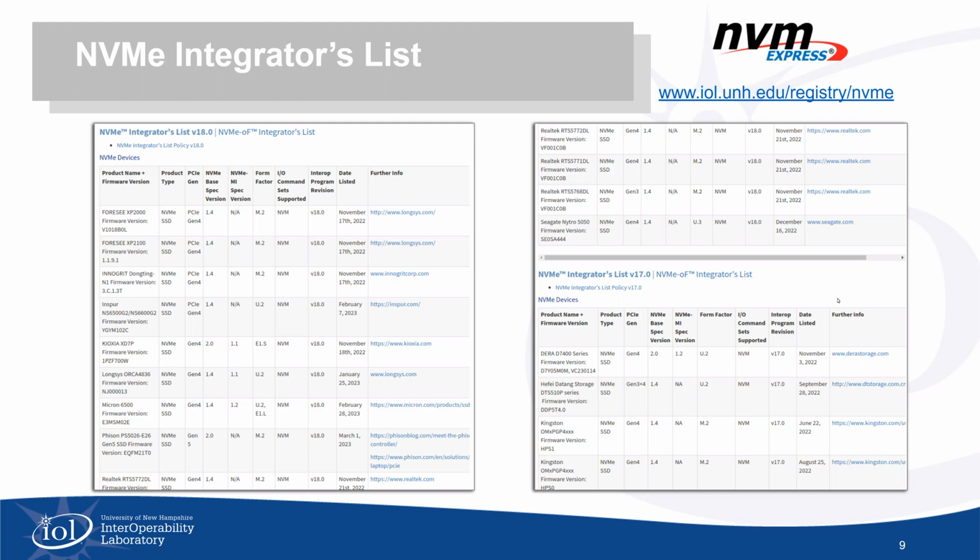So what is the required testing? For the most part, if you're just testing an NVMe SSD, you need to make sure that it passes the NVM command set conformance, NVMe transport conformance, whether it's PCIe or some other over fabrics transport. It needs to pass the specific transport interoperability testing, and if it supports NVMe MI, it should also pass that,